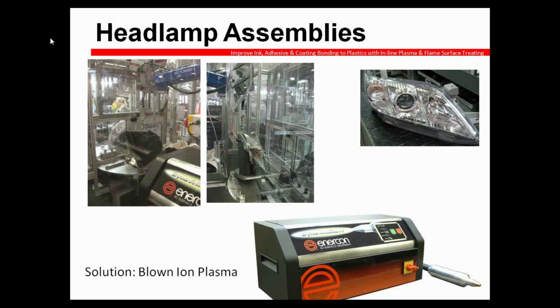It really doesn't add a lot of cycle time to it because it's already a robot already ready to go and programmed for that adhesive. So it's treating at a very fast rate, typically 100 linear feet per minute, in order to basically just apply the adhesive and move on to the next cell. I have a couple photos of what that would look like. A few of our customers have been gracious enough and shared those photos of them using an Enercon system here.